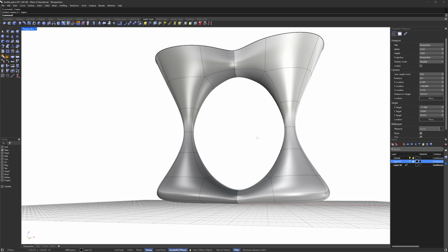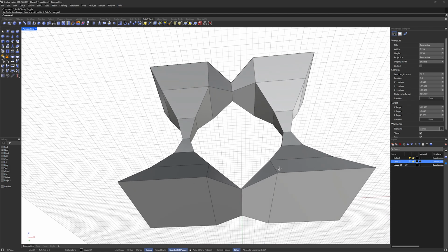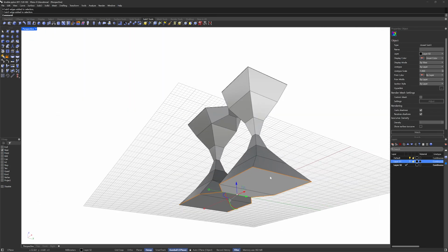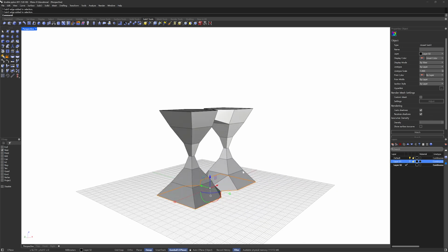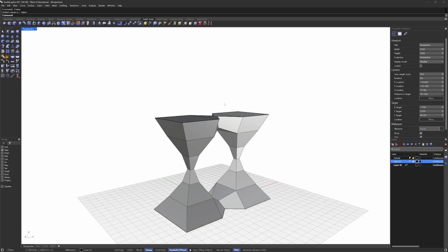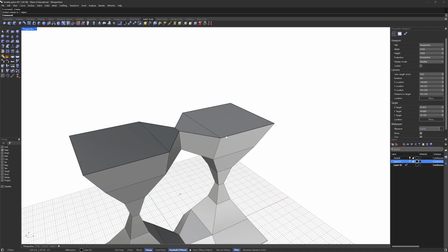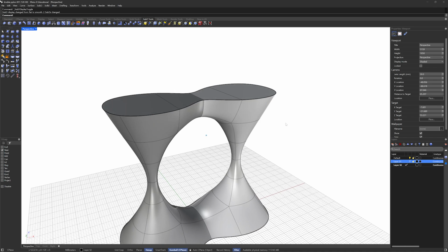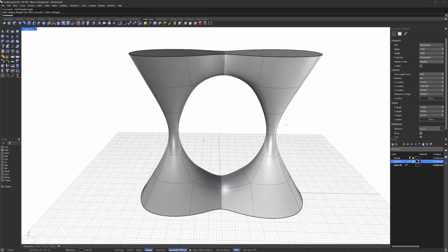Again, it's going to be easier if I go to the box mode. So I'm just hitting Tab, Control-Shift, and double-click. There's the edge there, and this edge here. So we'll do the right-click, hard crease. And you can see it actually lights up a little bit thicker edge there than this edge there. So that top creased edge will be more noticeable. All right, hit Tab. And that's pretty close to the final.